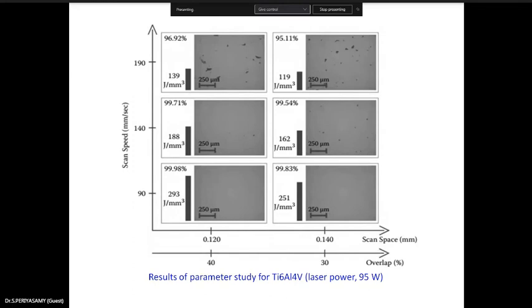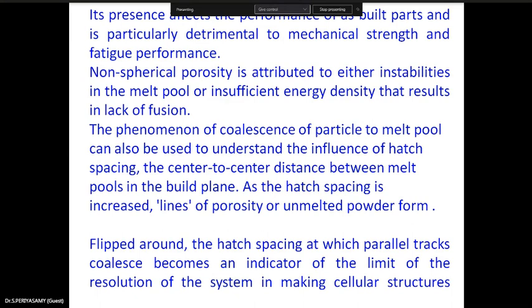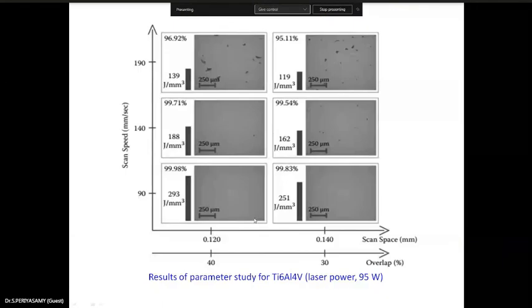Then you have a semi-reflective dichroic mirror. The laser source output comes, is focused, and strikes the melt pool. In between you have an optical filter, the beam splitter, then the detector. You have a detector on the upper side, then a photodiode with focusing optics, and image capture also. So here you can continuously monitor it.